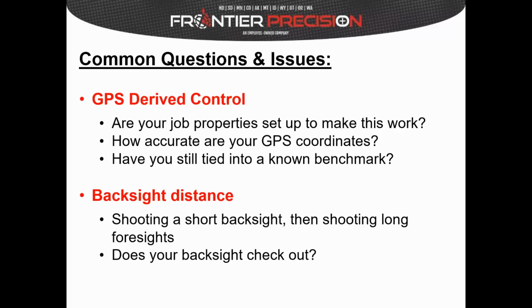When you're doing a station setup, you should be reviewing that station setup every time before you store anything. I get a lot of job files sent to me saying, hey, we set up on the wrong point, or hey, we measured the wrong backsight, can you fix it for me? I like to say most of the time, yes, we can, but depending upon how complex the project is and how much work was done off of an incorrect setup, sometimes we can't salvage it. Sometimes it just can't be fixed.